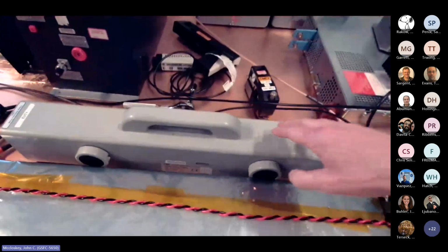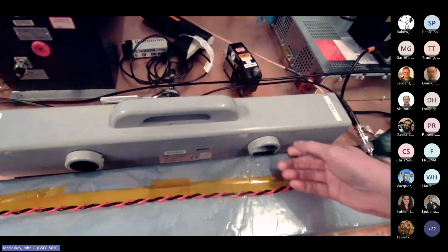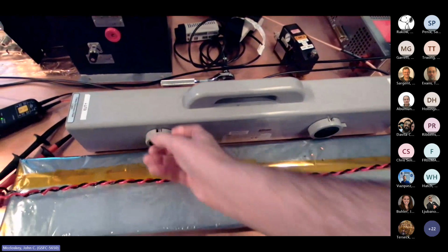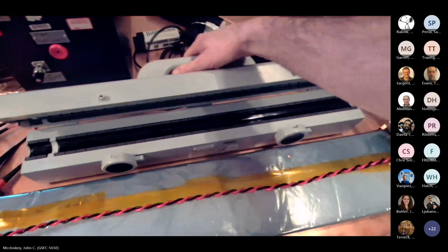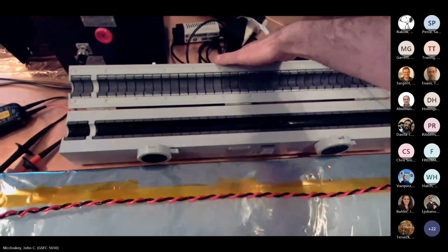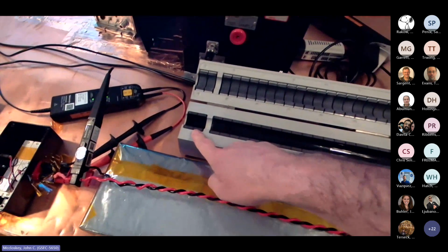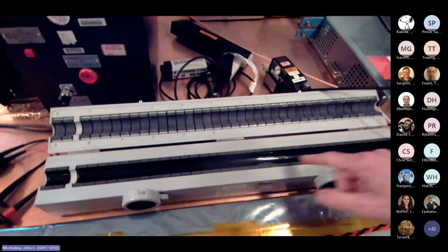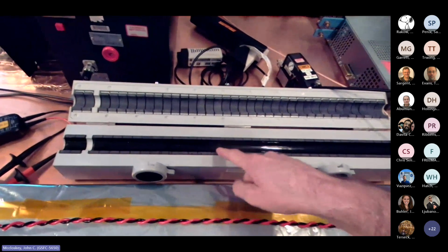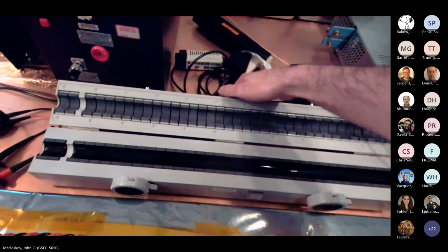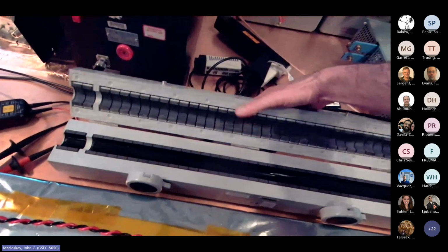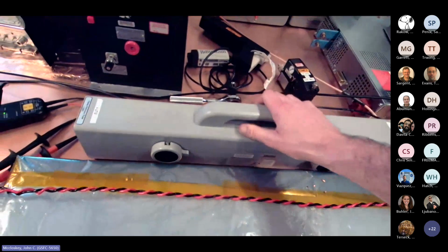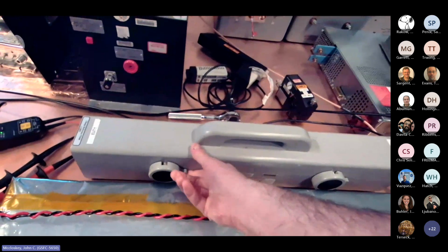So this is the absorbing clamp. It's the same one that's in that photograph, and it has a couple little wheels here to open it up. It has a current probe element here, and here's your series of ferrite absorbers. These are your absorbing elements, and at low frequencies they will be inductive, but then they are more absorptive above about 30 megahertz.